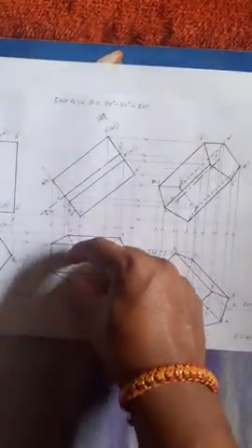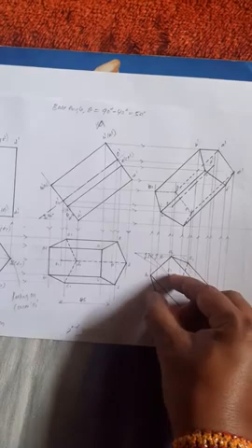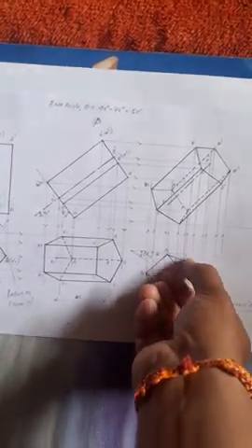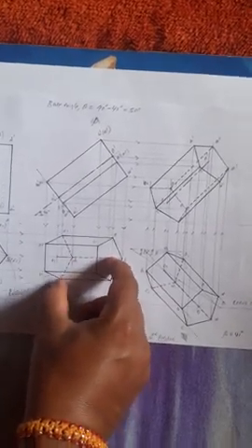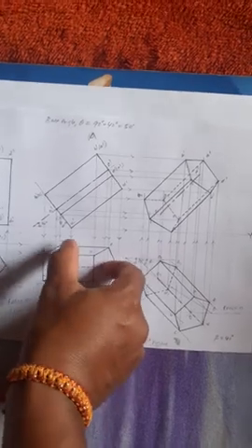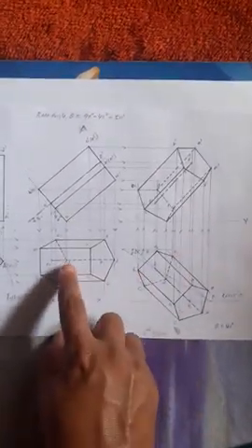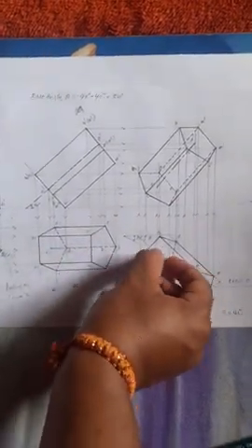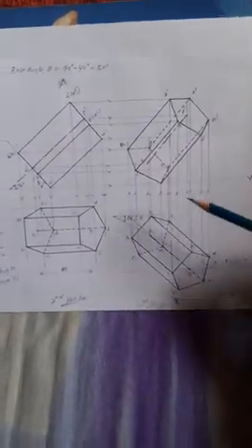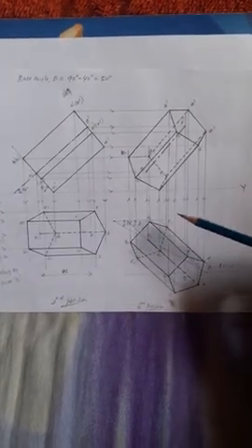Similarly, O1 C is equal to O1 E. Draw an arc of O1 C, that is equal to O1 E. Then O to C is the radius, O to E is the radius. Draw arcs from O to C and O to E; you will get C1 and E1. Similarly, on O1 O we will get D1, right? Measure O1 to D1. Now we will get the bottom face corners, or base corners, A1, B1, C1, D1, E1.